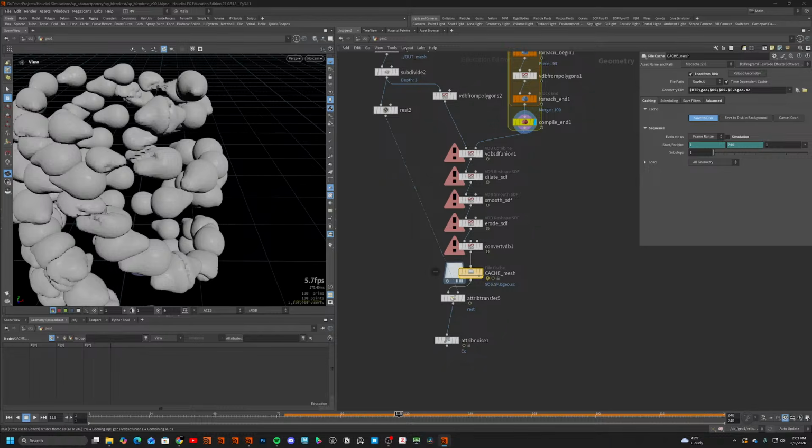So yeah, because we don't want sliding textures, we can use our rest position of our mesh here, of these spheres that are static, and mix it with our rest position. Not really mix the rest positions, but we need to mix the outcome of the rest positions, because otherwise we get like a stretched out rest thing. So we just need to blend our textures in the shader or color attribute and not the textures themselves. But yeah, wait, let's see.